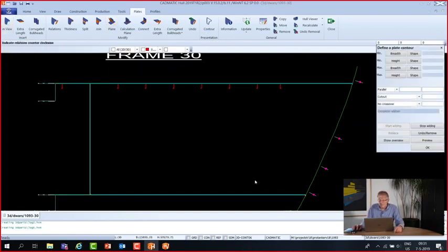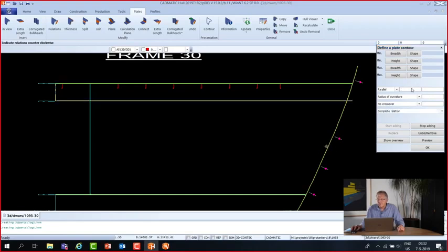You can start wherever you want for the defining. So I'm starting on the lower deck. I want to have a cutout of 75 millimeters. Then I continue along the hull line, the upper deck, connect to the port side girder, and now I once again select the deck to get an offset from it, 500 millimeters, and I'd like to have a radius of 300 in the corner somewhere here, and to end with an offset from the hull line, also 500 millimeters.